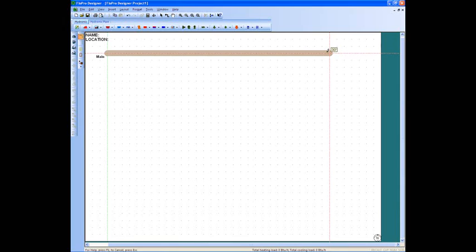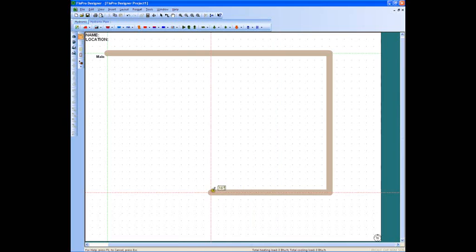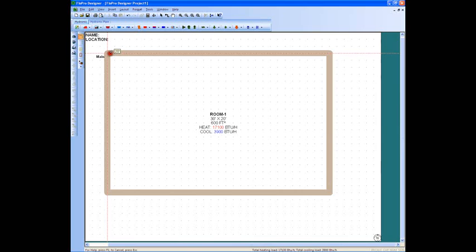At this point I want to change directions, so that is another left click on the mouse, and now we're going to change directions and go down, and we'll go down to 20 feet. And we'll stop at 20. Another left click, we change directions again, and we'll go over to the left and draw another 30-foot wall. And once we get over to that green line, and we can see the 30, so we always know where we are, left click again and go up, and we'll intersect with our first 30-foot wall. And once we get there, we left click again, and that stops it.